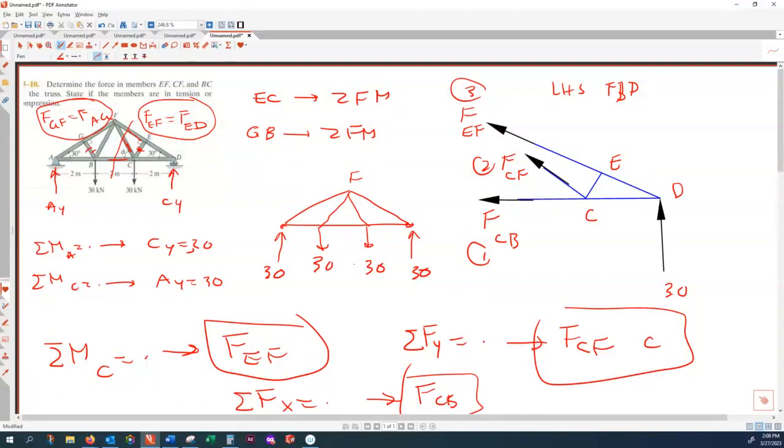And even with that, there should be a certain procedure. So you have to decide which joint is solvable. And then by solving that, you transfer its identified forces to the next step to reduce the number of unknowns. And then you keep going until all forces or the required forces are determined. Also today, we introduced the third technique, that was method of section. And method of section is particularly useful when you only are interested in few internal forces, not the entire forces.